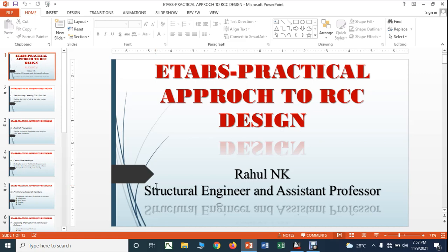I clearly wanted to make one thing clear: the column positions and the beam positions we did initially, based on the plan given by the architect, are not final. They are just preliminary positions of the columns and beams. At the end, when we are doing the final design, we are definitely going to change the positions of the beams and columns without affecting the architectural design, as per the client's requirement.